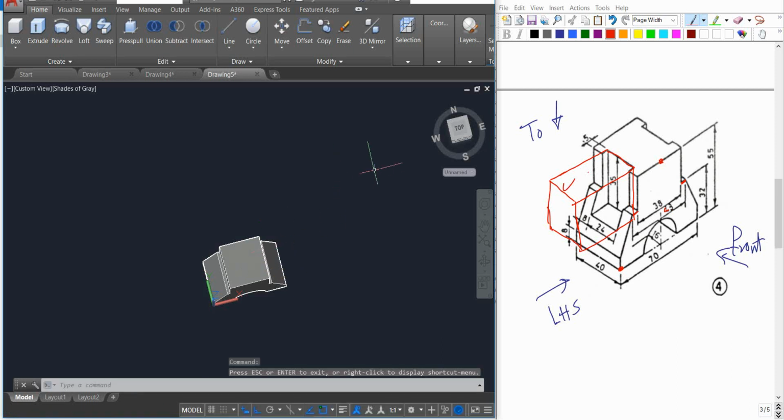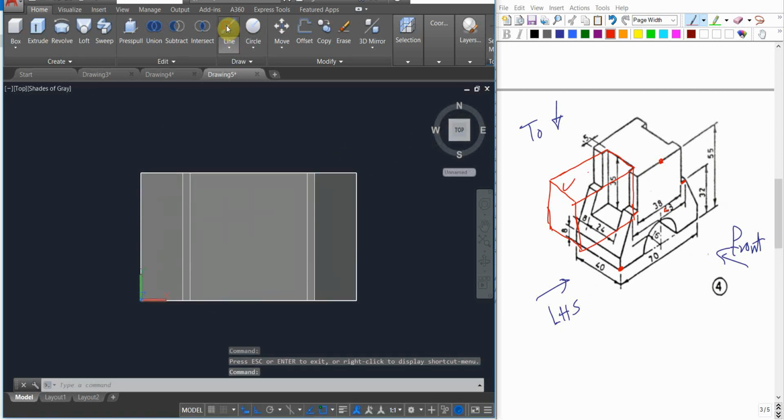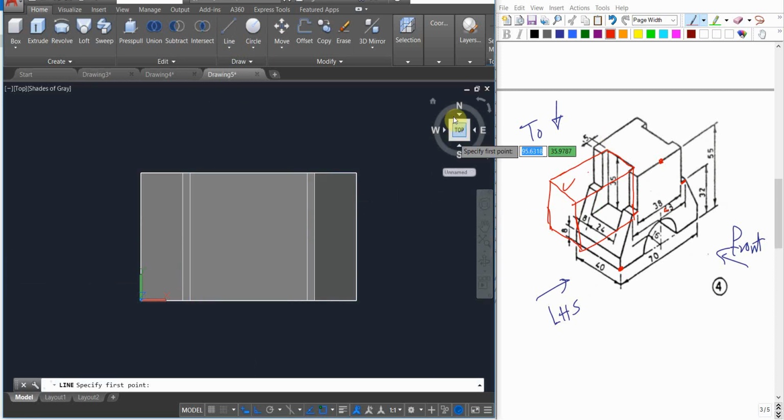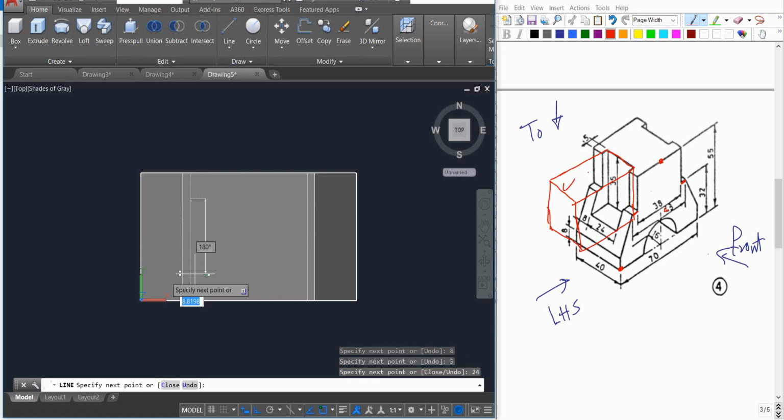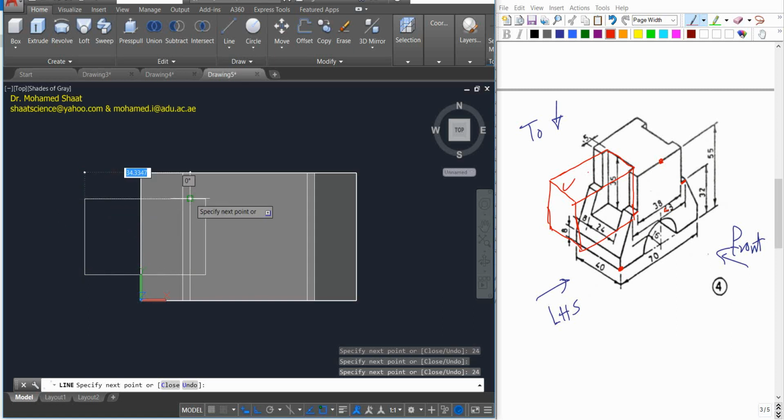Okay, in this way. So this should be the top view, and make sure that you can clearly see the lines from this point, which should be this point. You're just gonna go down here 8 millimeter, and you're gonna move to the right with 5 millimeter. Then we're gonna have here the 24, and extend with any length. Make sure that you entirely intersect or cover the shape, and going next to this point with this height, or you can go up with 24 and then close the shape.